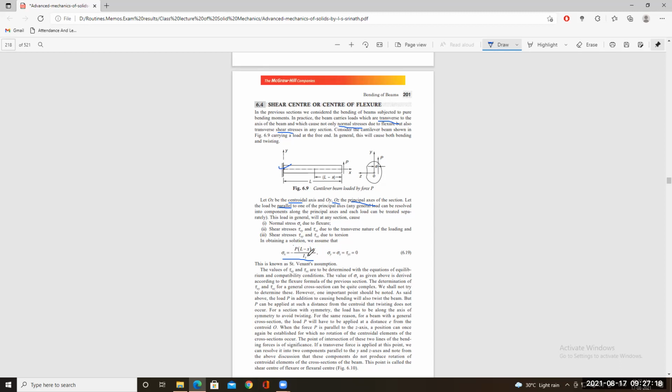Here there is the moment of inertia I, which is the second moment of inertia along the z axis, meaning z is along this axis itself. It is the distance of the cross section from here or here along z, multiplied by z twice, so it will have z square. The cross section area multiplied by the distance z square is the second moment of inertia of the element itself.